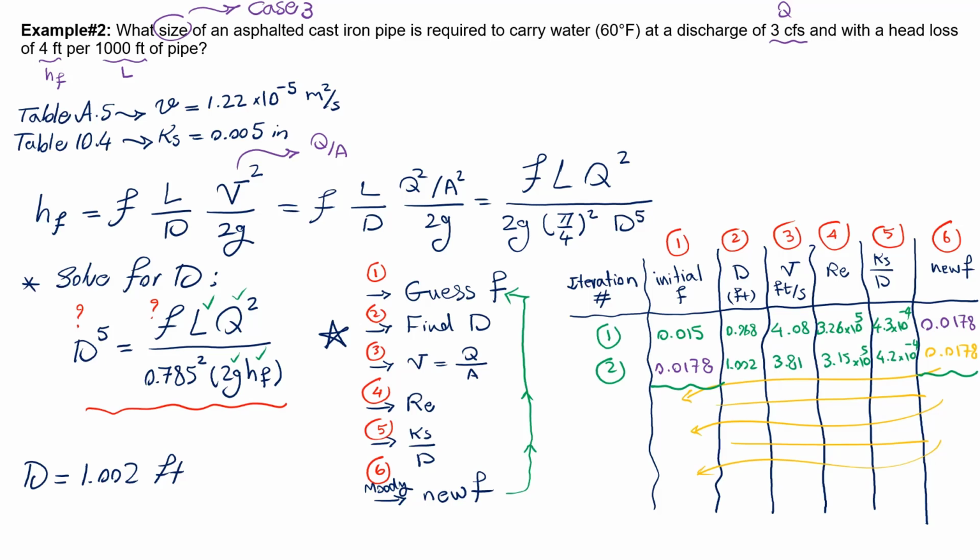However, no manufacturer is going to manufacture a pipe this big, right? Because take a look at the digits after the decimal point. So because no manufacturer is going to manufacture such pipe, we are going to recommend the closest round pipe, which would be 1.00 feet. And that would be our recommendation for the pipe size, and this was a design problem.